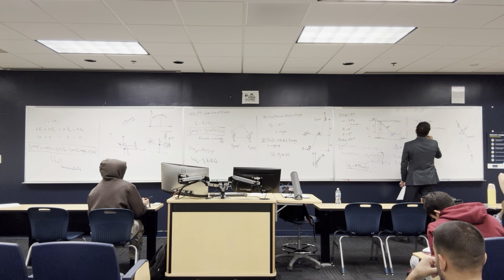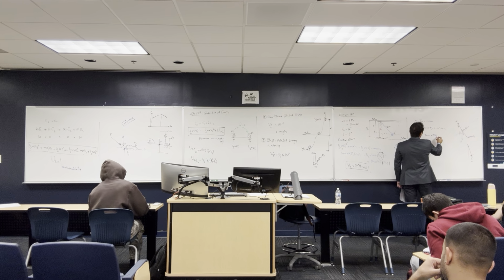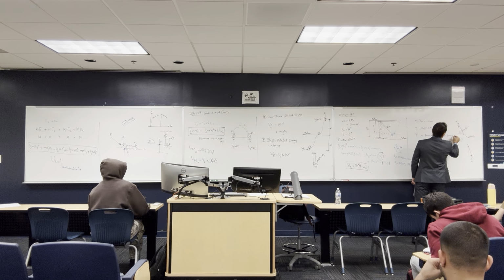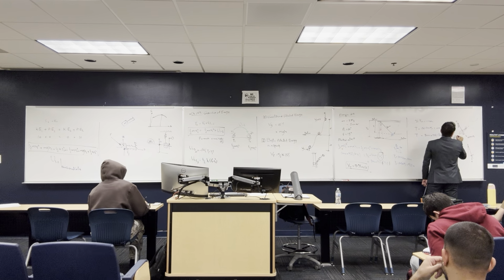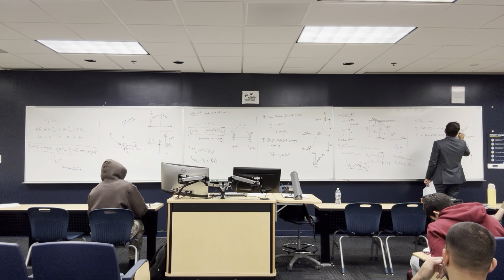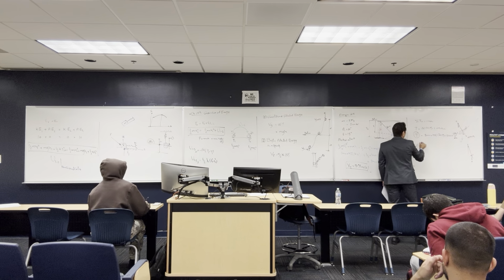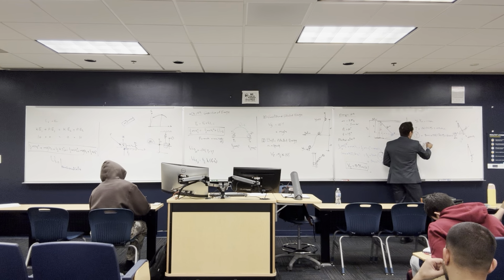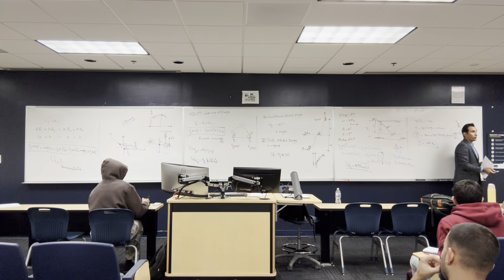Minus W, which is 8,000 kilograms multiplied by 9.81 to convert it to weight, and then cosine 15, is going to equal 8,000 multiplied by AN, which is V squared that I got here, 13.51, over rho, which is 20 meters. That's one single equation in T, and once you solve it, T is going to be equal to 149 newtons. So that's the solution.